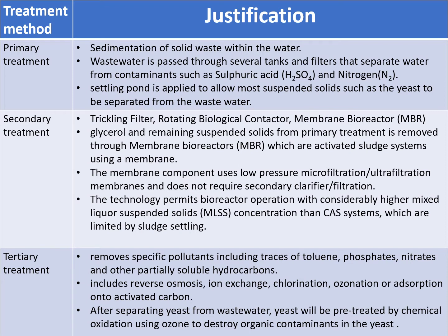The secondary treatment commonly includes a trickling filter, rotating biological contactor (RBC), and membrane bioreactor (MBR). In our plant, glycerol and remaining suspended solids from primary treatment are further removed through membrane bioreactors, which are actually activated sludge systems using a membrane.